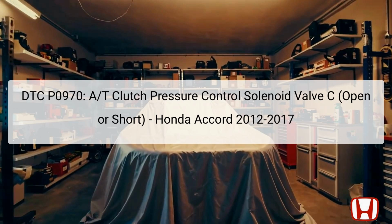The solenoid plays a critical role in regulating hydraulic pressure in the automatic transmission, thereby affecting gear shifts and overall performance. It's important to note that this issue is strictly electrical and not caused by any mechanical problems within the transmission itself. The code can often stem from wiring faults, bad connections, or a defective solenoid, which must be accurately diagnosed before any repair attempts are made.